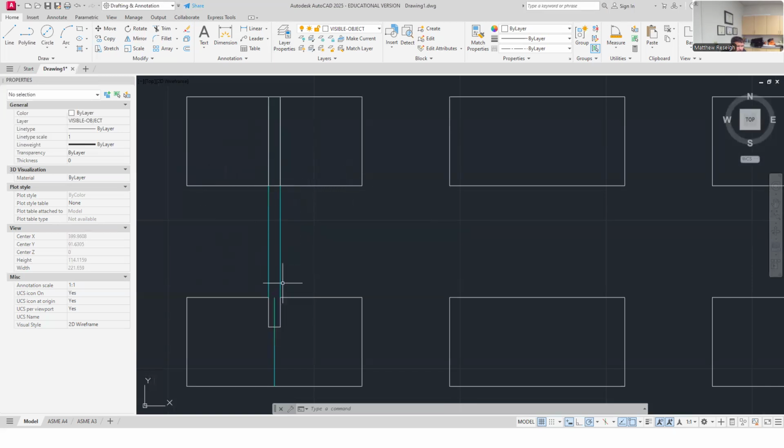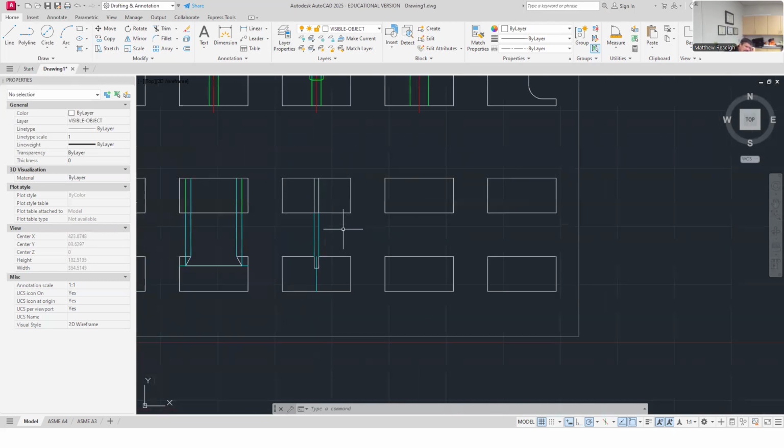where this surface appears as a line is right here. And even though it's cut through at the top, the visible line would still exist here because that surface still is intact all through here. So potentially this very bottom edge here would still be a solid line. So you have to be careful on what to trim, what is visible and what's not.